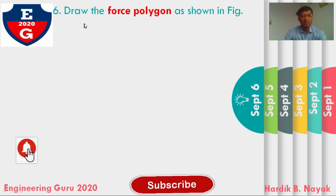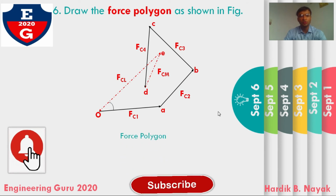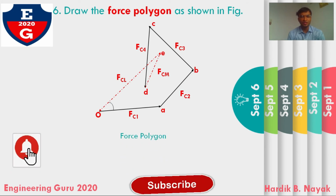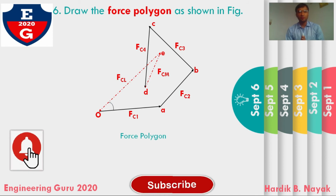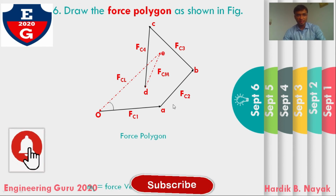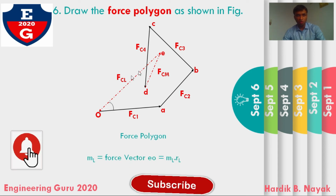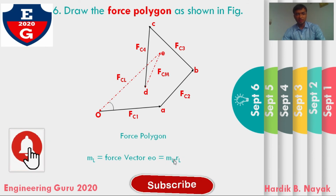Now final step, draw the force polygon. So how to draw this force polygon? We have to take FC1, FC2, FC3 and FC4 from the table column number 4. For how to draw the force polygon, you can refer to my previous video on graphical method and analytical method of solving problems. In this figure you can see the vector OE, this is the balancing force vector OE, so you can find ML, RL from this force polygon.